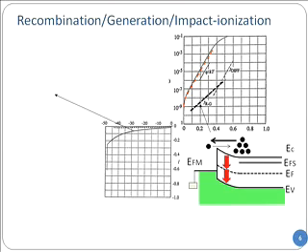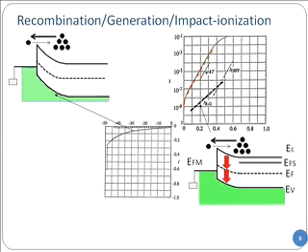What about the reverse side? On the reverse side, again, you know that this is exactly the same. This time this is reverse biased. So instead of recombination, in this depletion region, you will have generation. So what is generation equal to? Minus n_i divided by tau, or 2 tau, right? So essentially, we will just have to integrate that. And once you integrate that, the only thing you realize is that the width of the depletion region is increasing with the square root of V. And as a result, my current will also keep increasing as the square root of V.